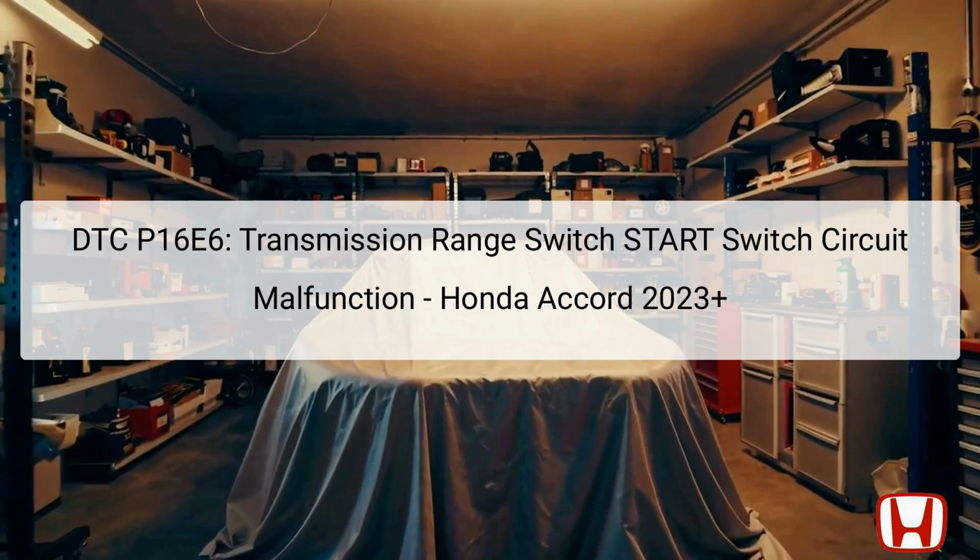DTC P16E6 indicates a malfunction in the transmission range switch's start switch circuit in the Honda Accord 2023 and newer models. The transmission range switch plays a critical role in ensuring the correct position of the transmission is recognized by the vehicle's powertrain control module, PCM. This switch effectively communicates the transmission's neutral, N, and park positions to the PCM, enabling proper engine starting and shifting.